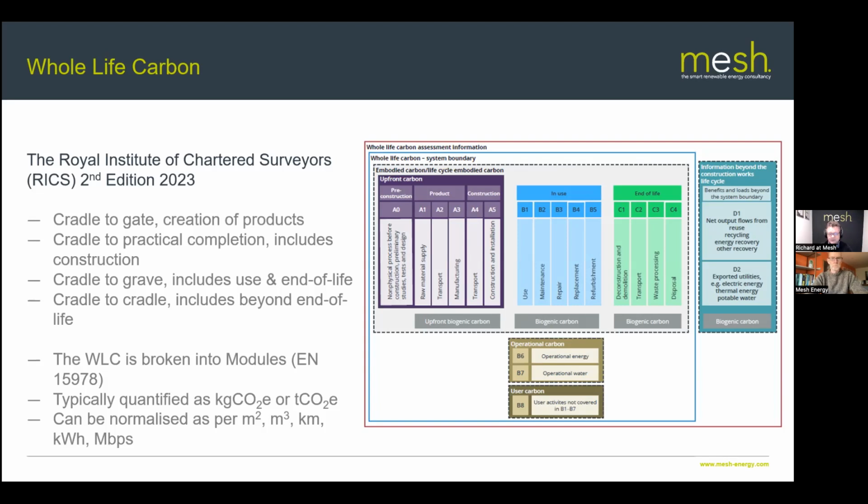I mean, they can be turned into different rates, but typically in the construction industry, we work in kilos or tons of CO2 equivalent per square meter. And you'll see that in the LETI and the REBA guidance. RICS, Institute of Structural Engineers, are all on board with this. So everybody from different aspects of the industry are now involved in this life cycle and understanding it, and also marrying that up with the digital plan of work. So we're all really starting to sing from the same hymn sheet in a significant manner.